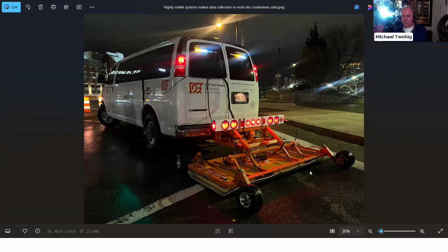underground utilities, but we've been able to identify the buried tram tracks, rails, anomalies, all the railroad sleepers that have been left from the old rail systems. We find voids all the time, bridge approach slabs. These are the things that normally don't show up in other people's documents. And we find that the Kontur system was the very best one for us to use for the environment we